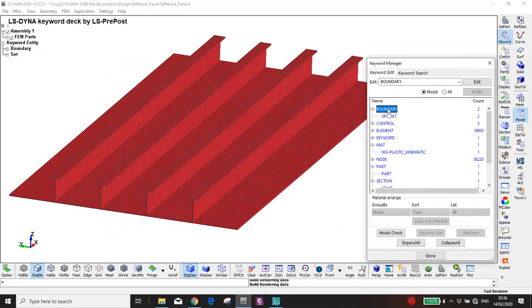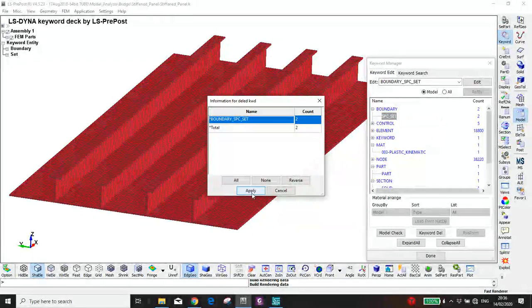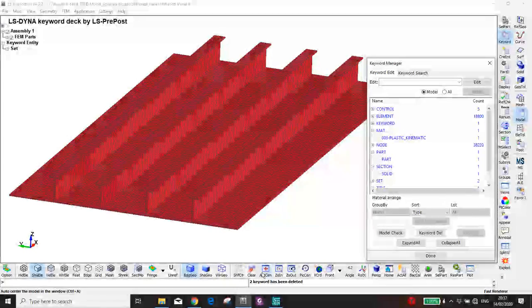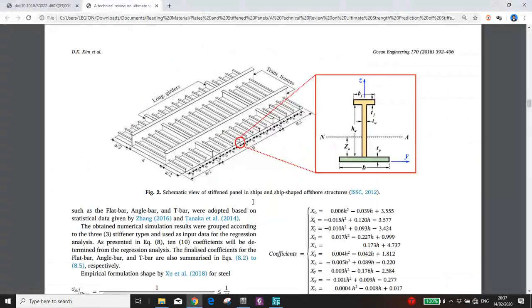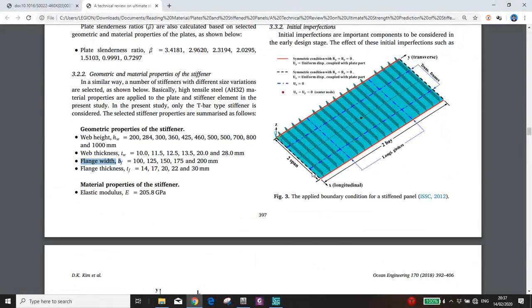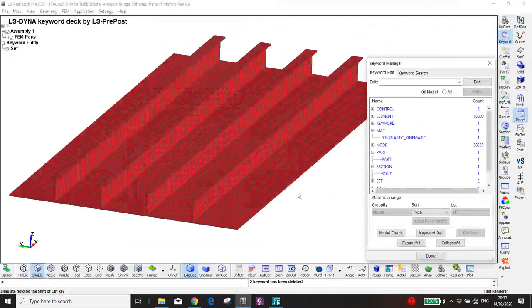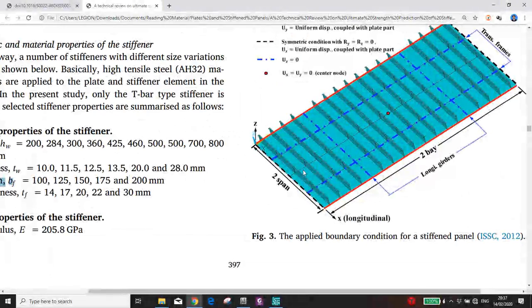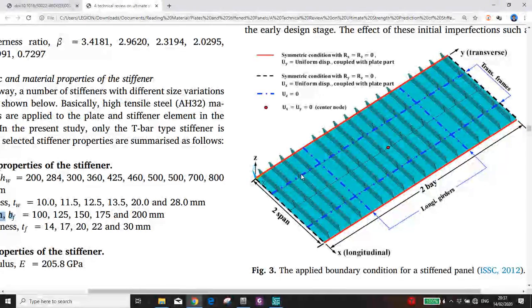Okay, boundary condition, this one I need to delete, of course, because it is attached to the old one, attached to our bridge that we destroyed already. So we see here the boundary conditions, we are making one of these. Okay, so the red one, no, we actually make one of this, the blue, so we want the blue part. So this one cannot move in X. So all these cannot move in X. Sorry, cannot move in Z. This blue one cannot move in Z, and this one says rotation equal to 0.